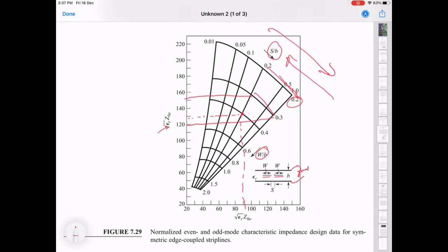that we are only putting V1 at one transmission line and then I'm bringing in another transmission line, then what the V1 and V2 will be. That, of course, will be different. But we are only talking about a given situation, when we excite even mode, odd mode will not get excited and vice versa. Is there some scaling effect of other on? That's another way of saying what I was saying, that somehow the overall capacitance needs to be... Charge distribution is taking place. Exactly. Yeah. Fringing effects.